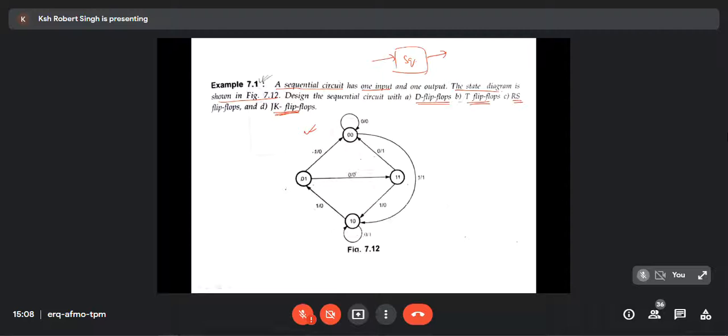If I reduce to 3 states, for example, it is also going to require 2 bits. So state reduction is just to make your task simple. Without state reduction you can also do it, but you will have more flip-flops. There is nothing wrong if you do it without reducing the states, but it is not a smart approach.